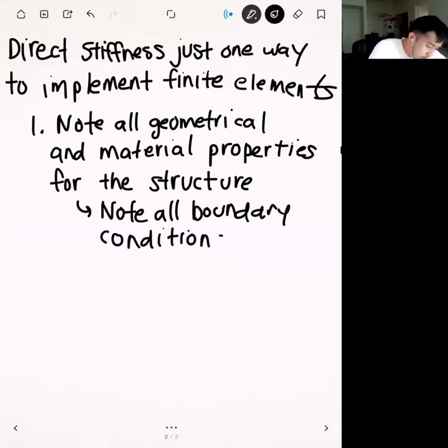Those boundary conditions are going to have a really big impact on our results. And later on, we need to manually input these into our global stiffness system. So that's the first thing: just take apart the structure, make sure you get every single detail and write them down properly. From here on, this is the familiar process that hopefully you all should be experts at now.